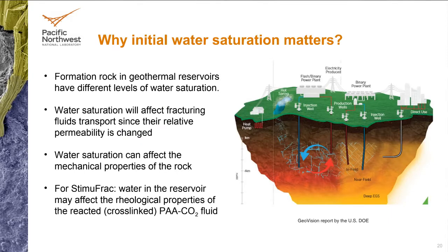And we also wanted to find out about water saturation of the rock, because in different regions of the United States and also in the world, the rock is saturated with different levels of water. So how can that water saturation impact the performance of the fluids, and is that impact associated with a change in mechanical properties of the rock because of the different level of water saturation, or is it associated with the mechanism of the fracturing itself for each fluid?